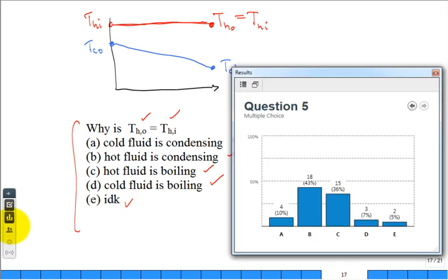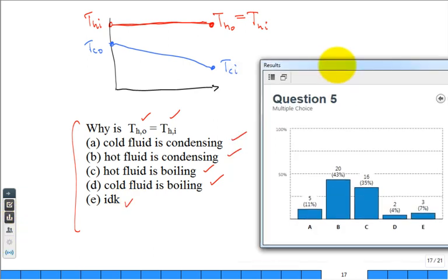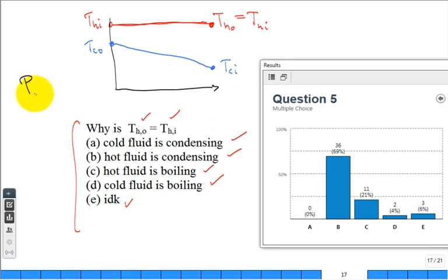So we'll just go ahead and talk about it a little bit here. So let's do this. One of the two fluid streams is undergoing a change of phase, because either boiling or condensation is a change of phase, isn't it? And if the general assumption is, I forgot to stress it, that the pressure on the cold side is about constant and the pressure on the hot fluid side is constant. There's not a big pressure drop that the hot fluid experiences. The heat exchanger is not a pressure drop device. It's a heat exchange device, and it does come with some modest pressure drop.